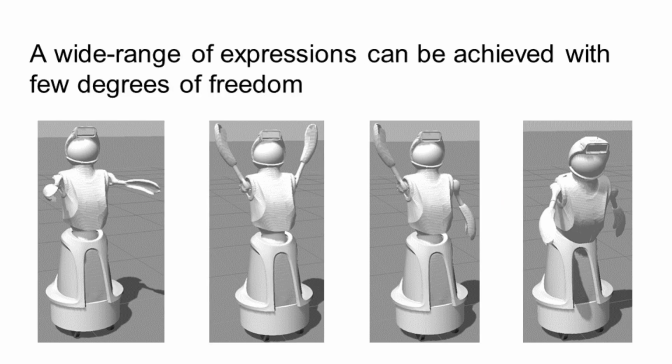Using this framework, we have designed a wide variety of behaviors based on Quori's available degrees of freedom. By adjusting the start positions, end positions, and speed of Quori's torso and arms, we can generate a large range of possible expressions and motions for Quori to perform. For example, one possible motion involves Quori slowly leaning backwards and raising its arms in the air. Another possible motion involves Quori quickly leaning forward and lowering a single arm. Thus, we can use varying speeds, degrees, and symmetries of movement in order to help differentiate the behaviors we produce.